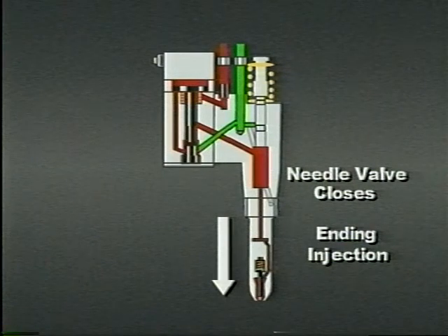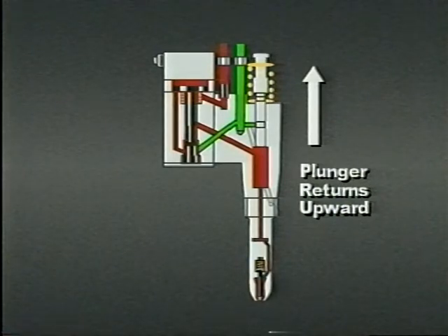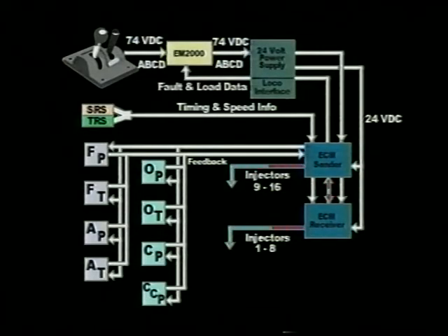Upon completion of the cycle, the pump plunger returns upward, drawing new fuel in through the poppet valve to refill the cylinder. Another interesting feature of the EMDEC system is its ability to monitor the electronic performance of the injector.